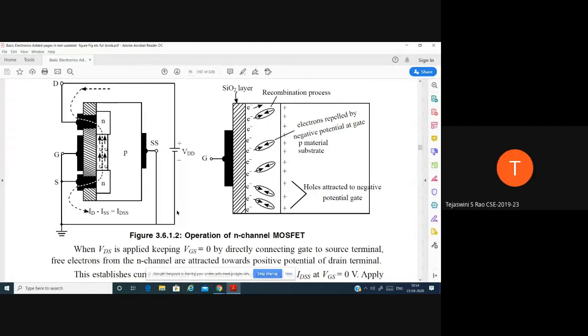The drain is connected to the positive terminal of the battery, and so a positive electric field is created at the n region that is connected to the positive terminal of the battery, and all the electrons move towards the positive electric field. Then, when the gate is connected to the positive of the supply and it is not grounded, a positive electric field is produced near the gate.